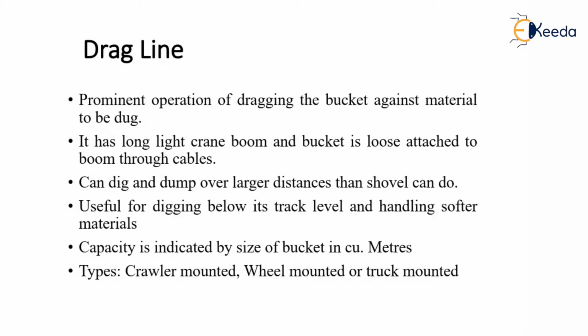It has a long, light-carrying boom and the bucket is loosely attached to the boom through cables. It can dig and dump over large distances, the same as the shovel can do. The dragline is useful for digging below its track level and handling softer materials. The capacity of the dragline is indicated by the size of the bucket in cubic meters. The types of draglines are crawler mounted, wheel mounted or truck mounted.